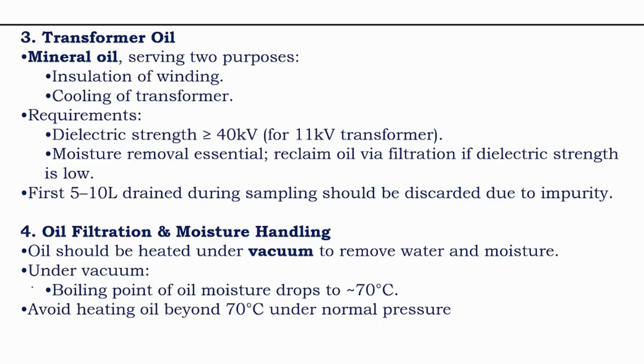The water molecules settle in the transformer main tank. So while taking samples for testing, we should discard 5 to 10 liters of oil and then take the oil for testing. And this oil should withstand 40 kV dielectric strength.